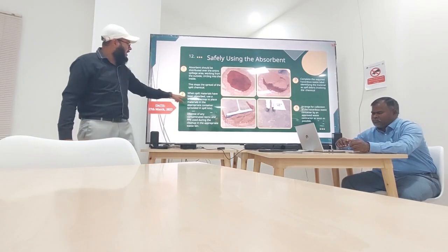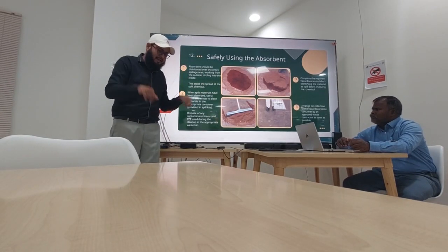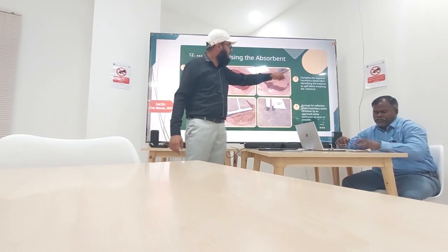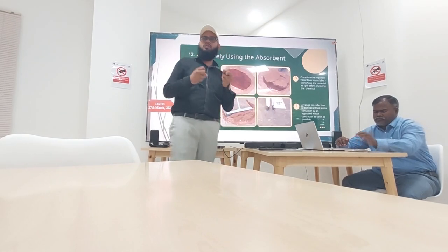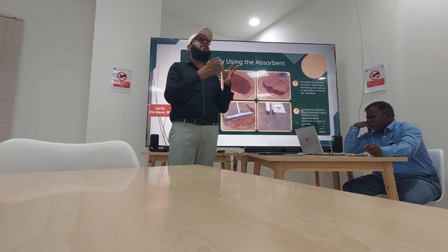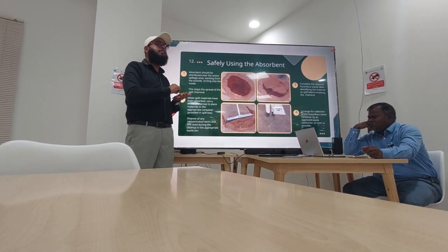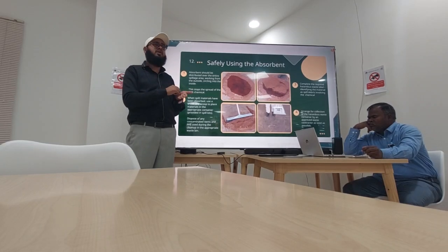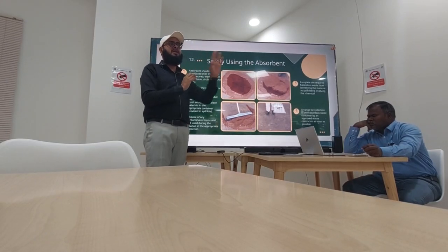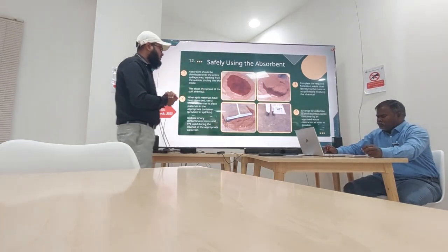When the spilled material has been absorbed, use a brush and a scoop. You can see here, once he is done with containing, putting and soaking, he is cleaning with the brush. Then complete the required hazard level, obviously very important. When you are first removing and cleaning that, you should properly put it in the trash bin or plastic bag. It should be properly labeled with everything: date of incident, what type of waste it is, so that everyone who sees it knows that this is actually a spill for collection. That's very common and generic.